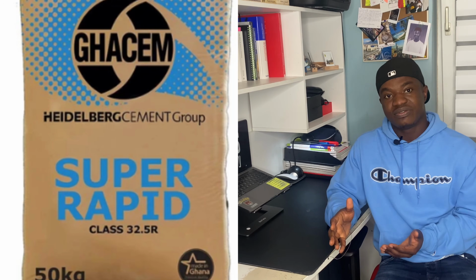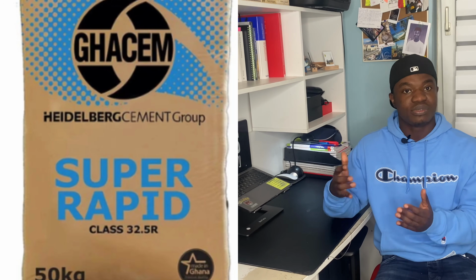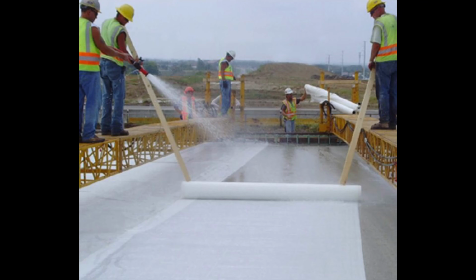Now I'm starting with the 32.5. Now with the 32.5, the grading is the compressive strength after 28 days. So after mixing the concrete with cement, you get to know that after 28 days of curing, the strength of the concrete is 32.5. That is for the gradings, that's for the strength of the concrete at 28 days of curing and passing through the hydration stage and all of that.